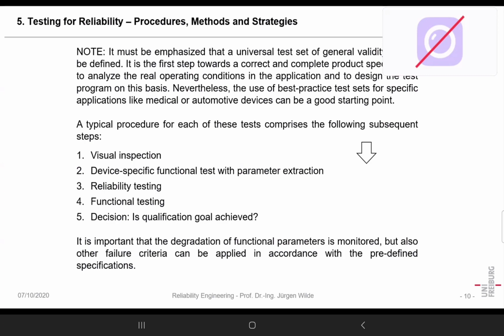Because that pressure sensor had a defect, its zero point was shifted, and that meant the anti-brake locking system would start operating at other conditions, so not under the controlled conditions, and in that way it would not function properly.